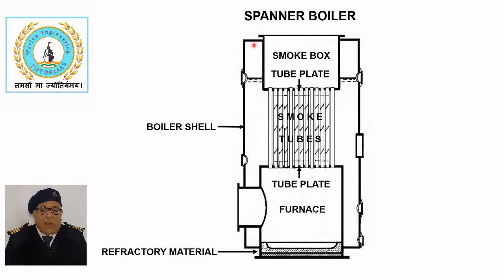No stays are required for the outer shell. However, the flat tube plates are supported by plain stay tubes, which are expanded and then welded into the tube plates.